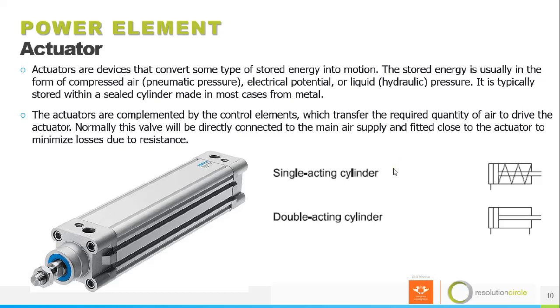The actuators are complemented by control elements which transfer the required quantity of air to drive the actuator. Normally this valve will be directly connected to the main supply and fitted close to the actuator to minimize losses due to resistance.